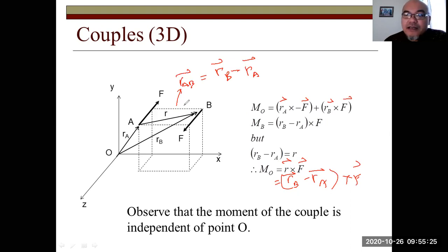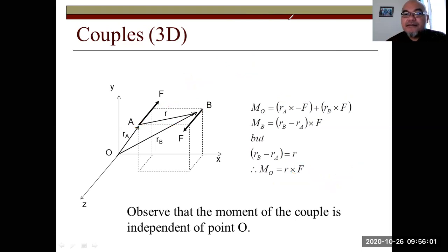What we care about now is only the vector from point A towards point B. So whenever you shift the two forces of the couple anywhere in the 3-dimensional space, they would still have the same result, similar to the previous examples in 2 dimensions. So in 3 dimensions, what matters is only the vector between the beginning point of A and the beginning point of the other force B.